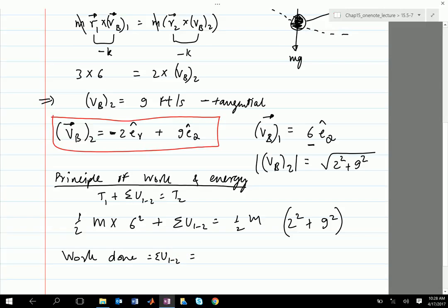What I get is 3.04 foot-pounds. By the way, mass is given as 4 lb. I think the book wants to make me think that it's 4 lb weight, so the mass is going to be 4 divided by 32.2. The 4 lb weight is the right way to say it, and not 4 lb.